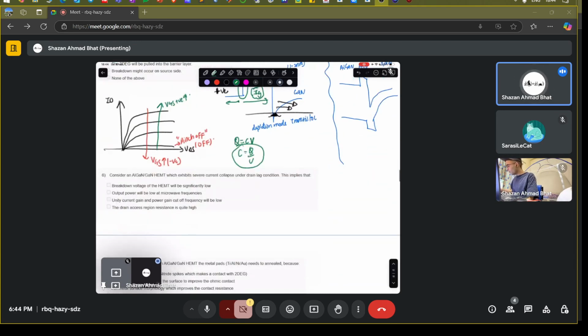So it's definitely going to alter the band diagram. If this is the band diagram before application of the positive gate voltage, then what is going to happen if you apply the positive voltage here? Positive basically pushes the Fermi level of the gate.